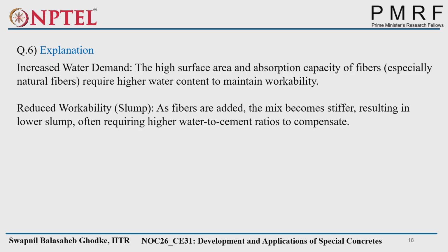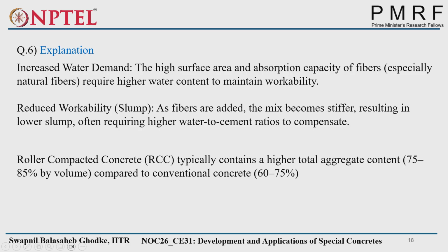Suppose you see most of the UHPC or most of the 3D printed concretes, in the case of 3D printed concrete, rebars or steel are not used. So that purpose is only why they are adding the fibers, to get some tensile strength. So more use is in the tensile strength only, and the compressive strength is observed to have a 10% reduction as per the literature.